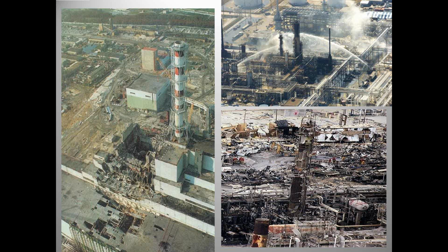Around 125,000 people killed, and another 400,000 affected in their health for years after that. BP Texas City, in the upper right-hand corner: filling a column, a simple process of starting a column up, turning the heater on, filling this column up. The level transmitter stops at 40%. The operator sees that and tries to increase the rate.